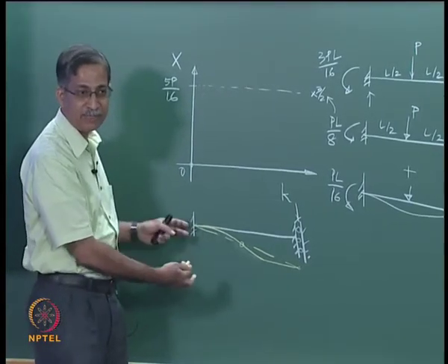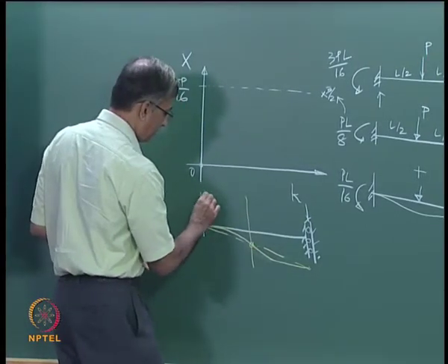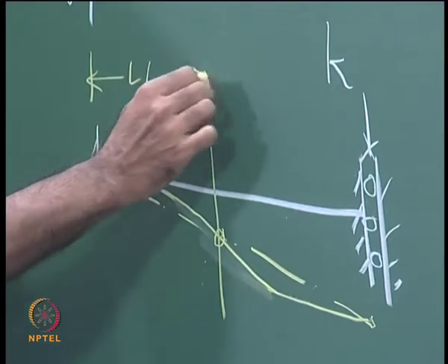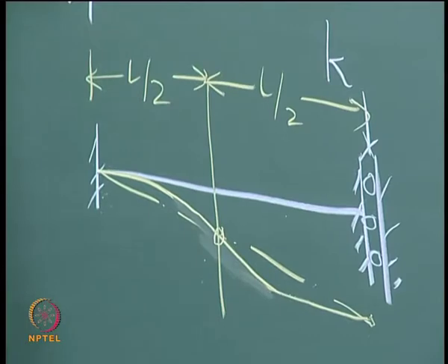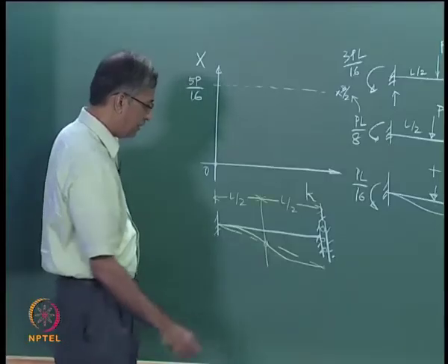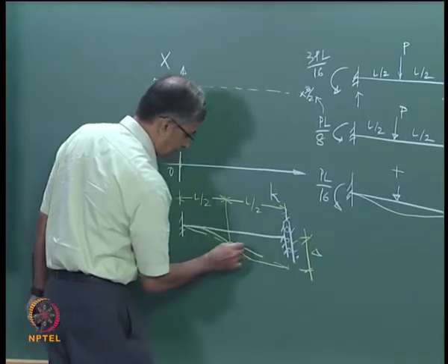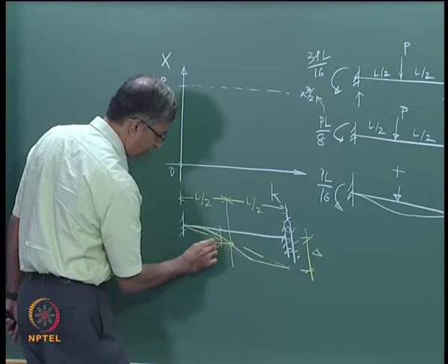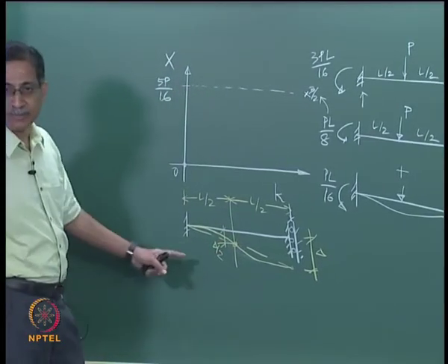So these are all reversible. So this point of contraflexure will always be in the middle of the beam, right. You keep moving it up and down, this chord rotation is going to be like that, and if this is delta, this has to be delta by 2. You are not convinced?